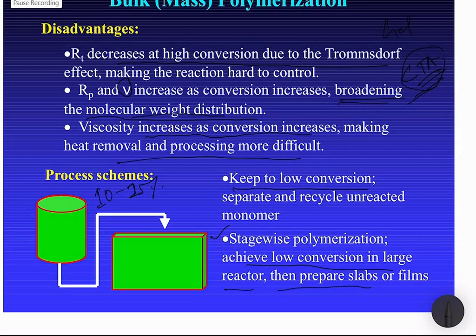they are being insulated of heat and electricity, so they will not naturally dissipate the heat, rather they will accumulate the heat within the polymeric mass. And because of the growth of viscosity, the stirring also does not remain too effective to dissipate the heat. So that way, a lot of heat is stored or accumulated within the polymeric mass, and that would create a lot of side reactions in the polymer as well.